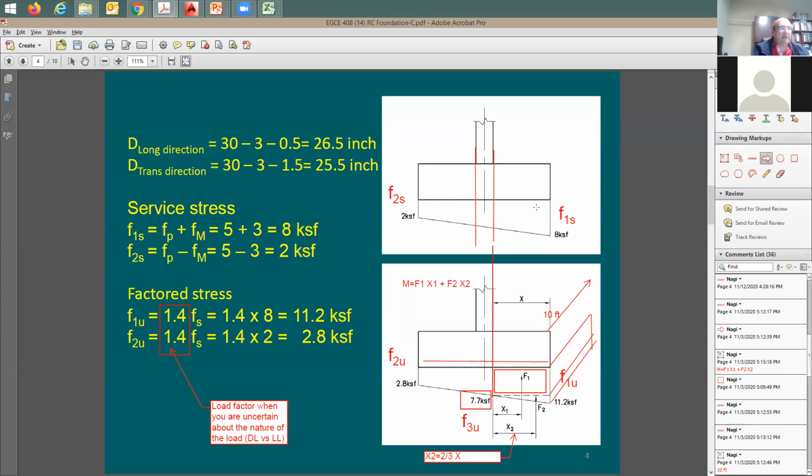You say this side, I'm going to have force coming this way. Now I need to know the point of application, which is the distance from this face to the point of application of the force. So you have the force value, and then you have this distance. It's going to get you one moment, and then you do the same thing from the other side. You have the force times the distance. Now, which one do you think is going to get you a higher moment? Is it going to be the right side or the left side? Right side? Yeah, absolutely the right side.